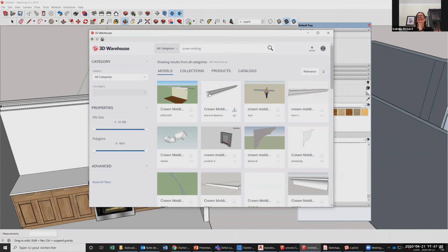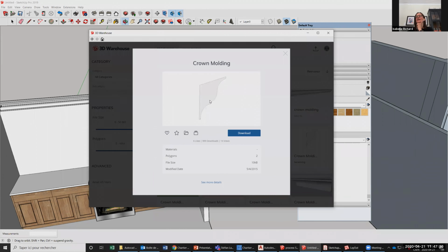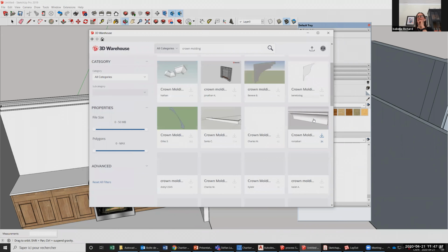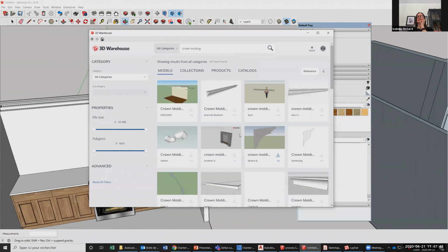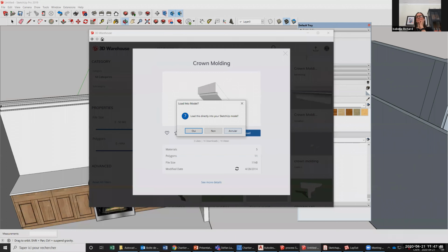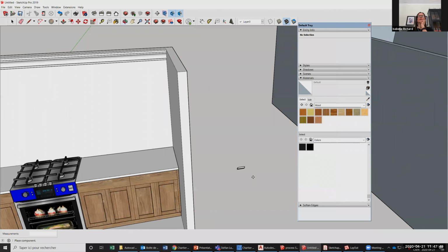Just to answer the last question, you don't pick those moldings, but you select those ones that are made out of just 2D drawings like that, so you can extrude it the way you want. All right, you don't select this one, you see. Or if you select a part of a crown molding like this, what you do is, well, you have to explode it.